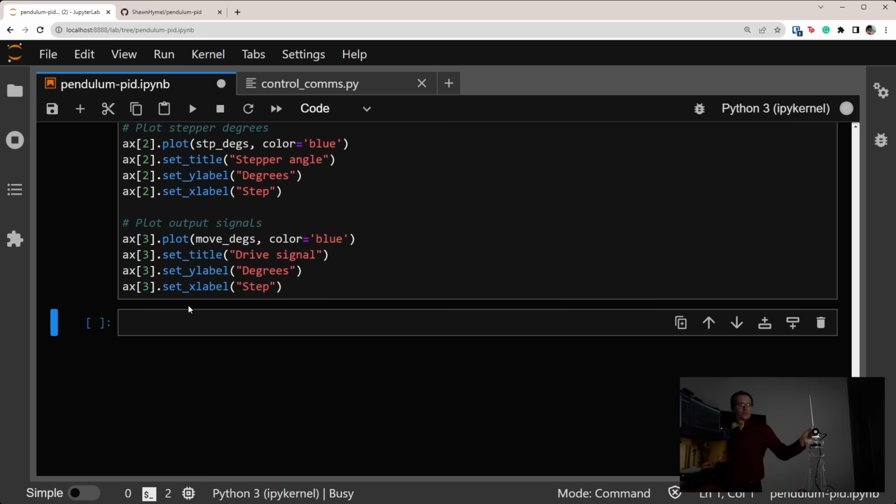We started with 0, which is a good place to start. I'm gonna guess 0.1 just to see what happens. Once again, this is usually lower than the Kp term, so let's try this. This is actually not too bad. Okay, let's take this down and take a look at our graph here. It's looking pretty good.